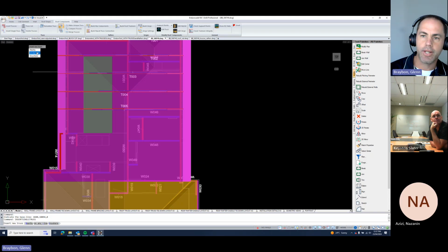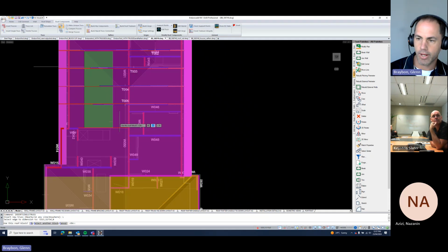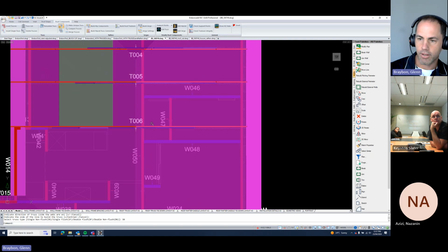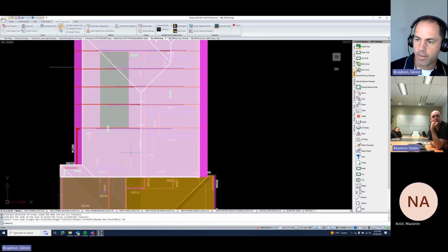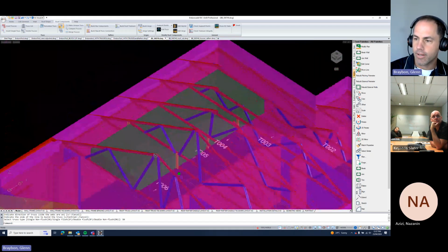So we can still insert on any line. So we want to insert. I know one of these doesn't work, but use this roof block. Okay. Indicate the direction of the truss. So which way are we going? We'll go minus. Use a lot of commands here, isn't there? We'll go the minus side, and we'll go single non-flush. I think that's the reason I don't use that, because it asks me so many questions. But yeah, you can see obviously we're building some roof blocks there. It's put that coffered in.